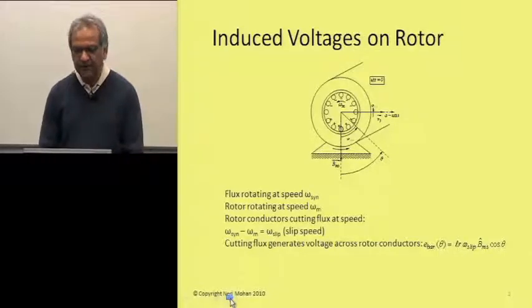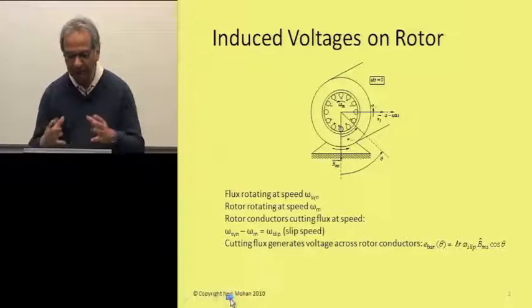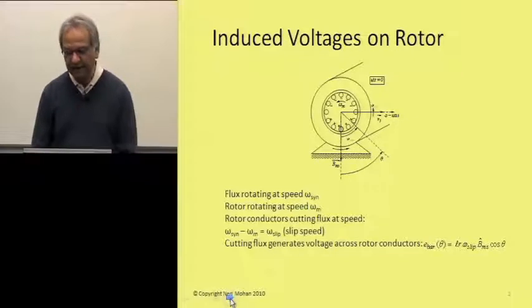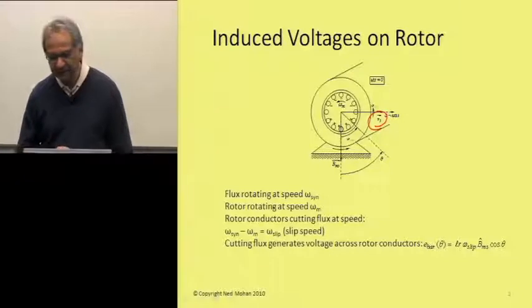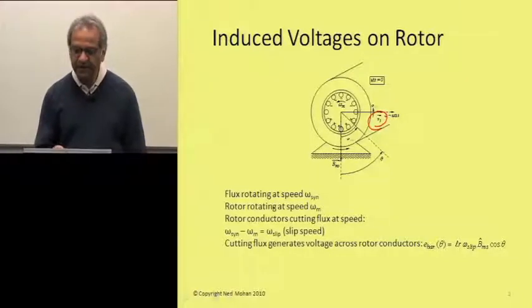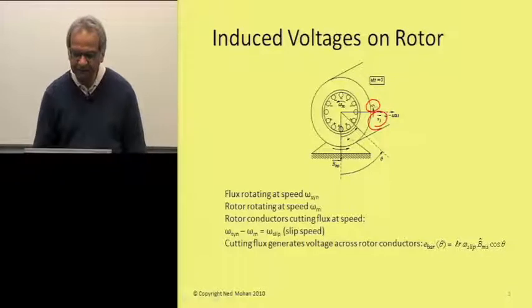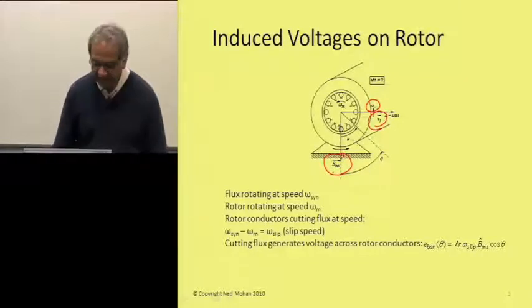First, let's assume that the rotor bars are somehow open in the sense that there's no current flowing, just for the sake of discussion, and we are applying certain voltages resulting in this stator voltage space vector, which is rotating at the synchronous speed, and it results in some magnetizing current which is drawn from the stator, and this flux density distribution is represented by the space vector, which is also rotating at the synchronous speed.